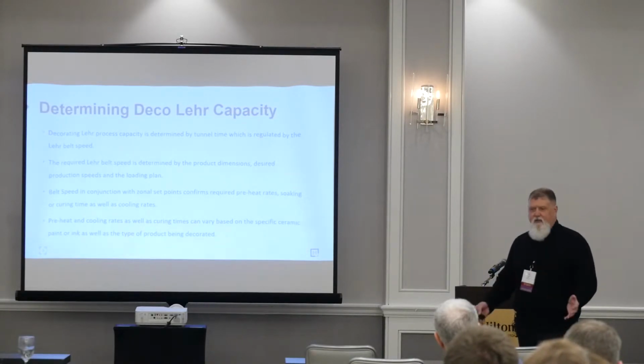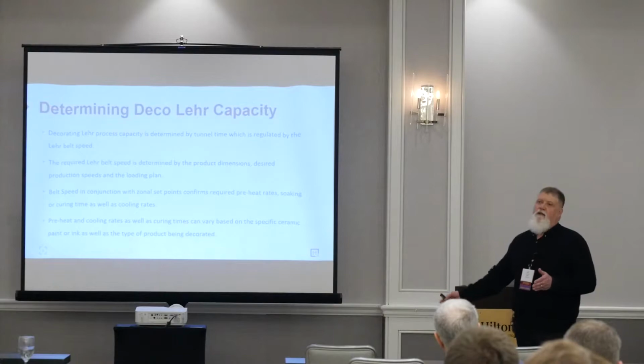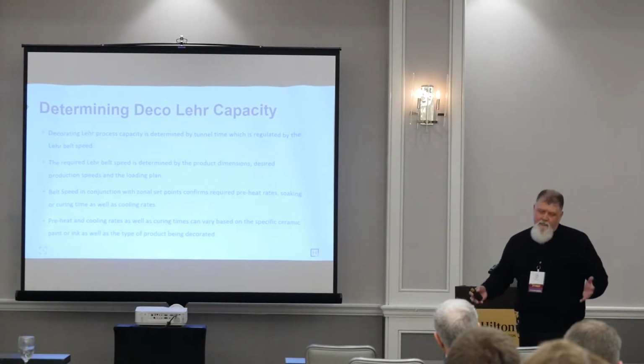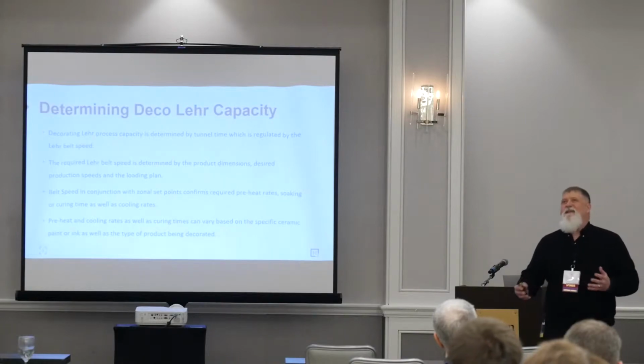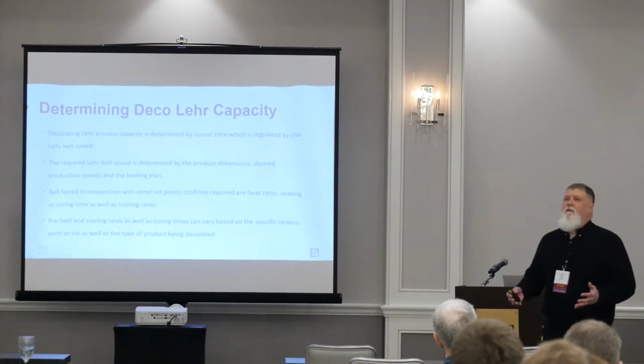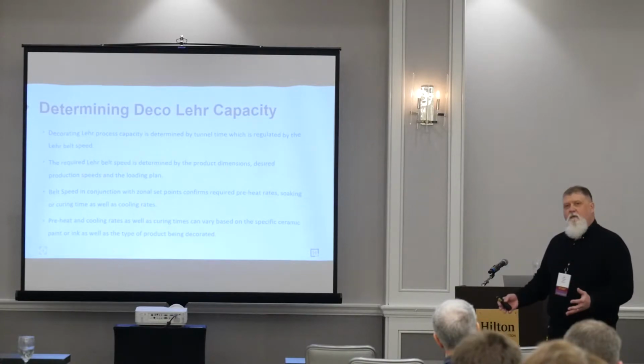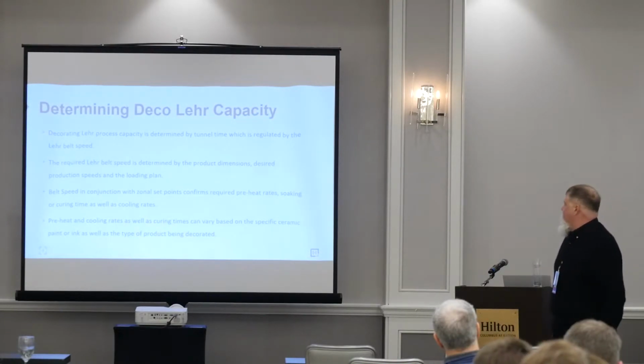If you're doing a low temperature product, that whole annealing phase goes away, and if you're doing ceramics, then typically the paint is going to determine what your heat up rates are and what your soaking times are, and not so much the actual ceramic item that you're decorating.